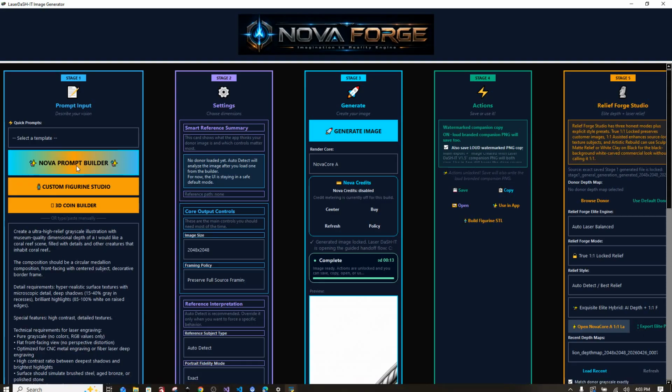Oh yeah, well the most important thing in Lightburn is when you double click on where you enter your speed and power, there's a switch in there called pass-through. Always make sure pass-through is on. That tells Lightburn to leave my photo alone. Do not further process it.